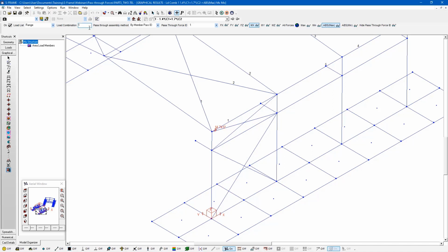I can also sum up different load combinations, so I have 3 in total. So I can say, let's look at load combinations 1 through 3, and maybe I'll get some different results. So I have 24, Fy is 4.2, and Fz 18. So in this situation, it looks like load combination number 1 was actually the governing for every single direction for this particular joint.